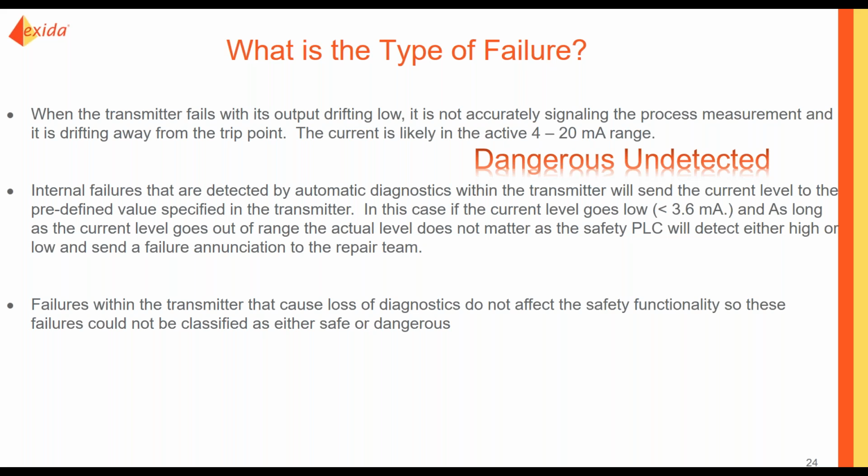However, the transmitter is not capable of responding to a demand during this time, so the failure would be classified as DD, or dangerous detected.